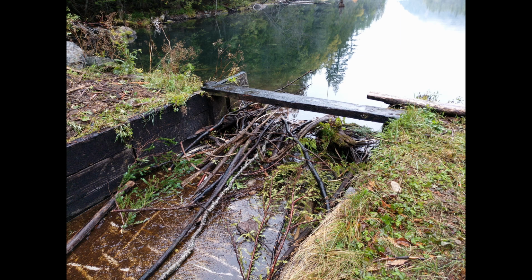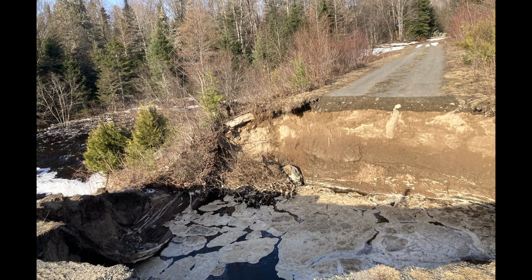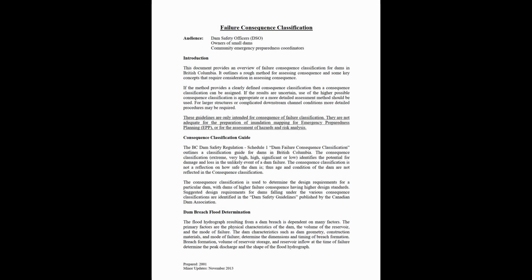Beavers often blocked the emergency spillways of the dams with branches, trees, and soil that had to be removed. The dams could fail with runoff from one major storm if the spillways were blocked. The BC Dam Safety Consequence Classification rating for the Violin Lake Dam was significant. The risks associated with failure were determined after modeling various hydraulic scenarios. The spillway for the Violin Lake South Dam needed repair.